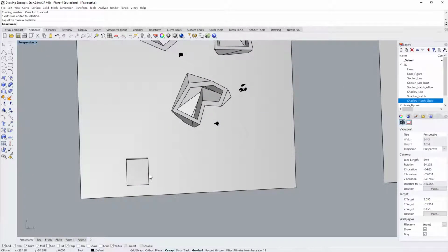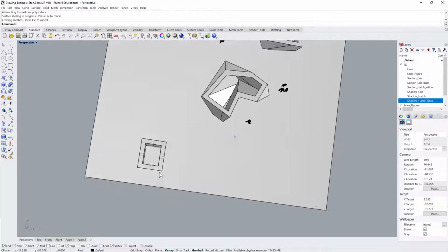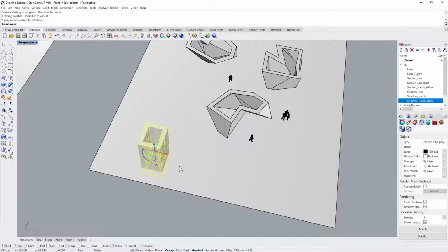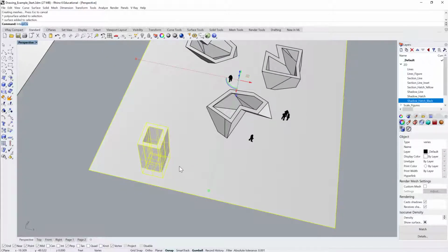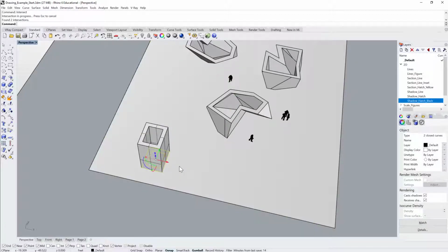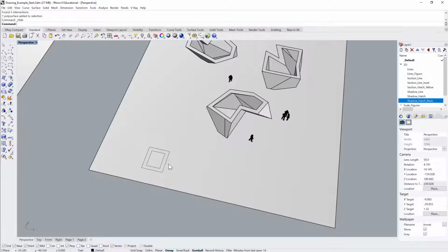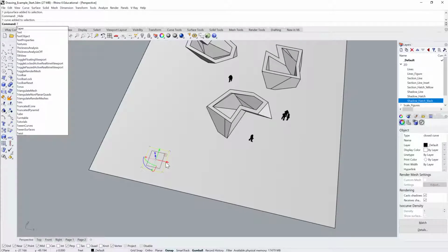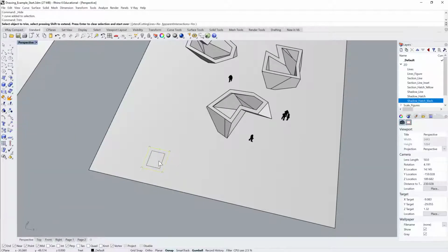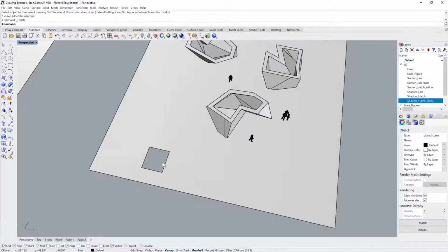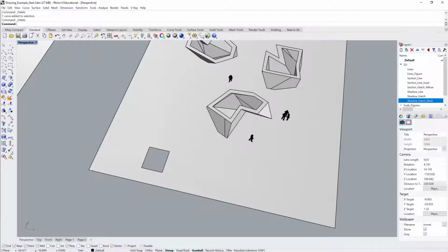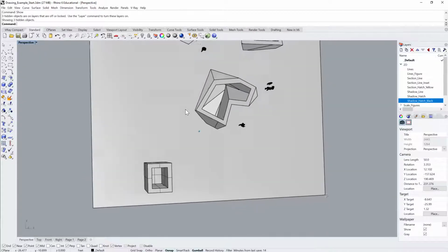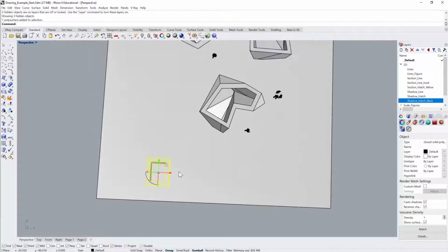So if you had geometry here, let's say I can't really trim the surface with this, but let's say I were looking down on this, and let me shell this. Okay, and I want to see down into it. What I could do is intersect these two things. Okay, hide this momentarily, take this, trim it. Okay, cool. Get rid of both of the lines. Show it. Okay, now I'm looking down into that object, right?